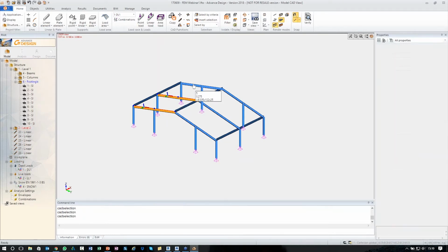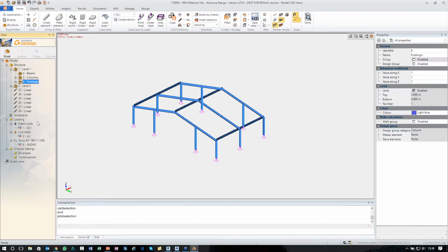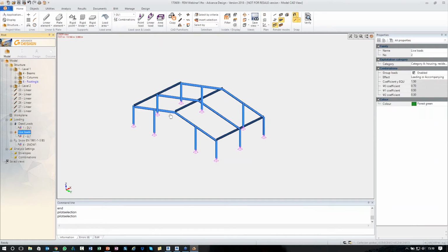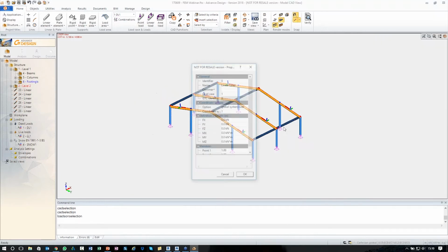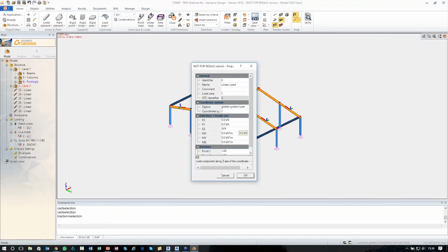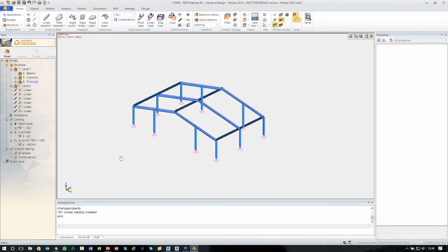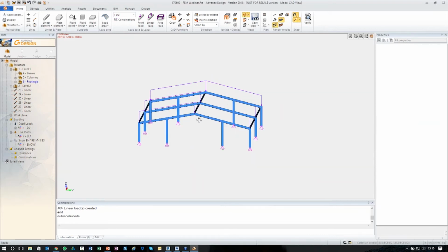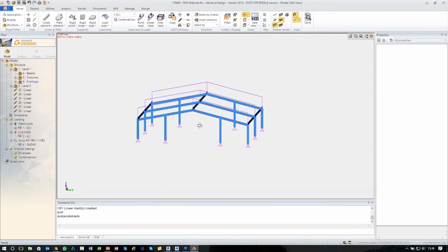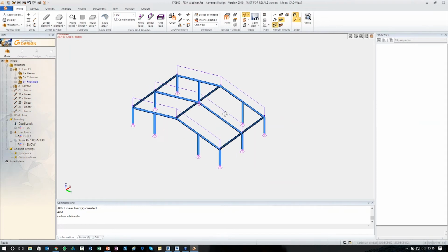What I would want to do then is go to my live loads and I'm just going to select my rafters. I'm not going to do a complete process. I'm just going to load these on selection, and I'm going to put a -2 load on there, and I'm just going to deselect and then loads auto tile. So you can see that I've loaded up the rafters.